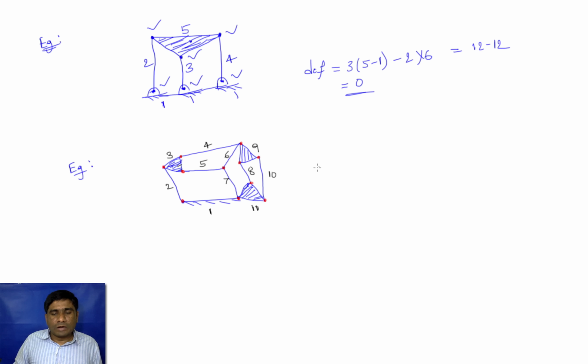So altogether what is the value of n? That is 11, and here we need to find out p1. So p1 is the number of pairs having degree of freedom 1. Between 1 and 2 it's only 1, plus between 2 and 3 again only 1, and between 3 and 4 and 3 and 5, 1 plus 1. So this is over, and this is also over. Next we come to this point.